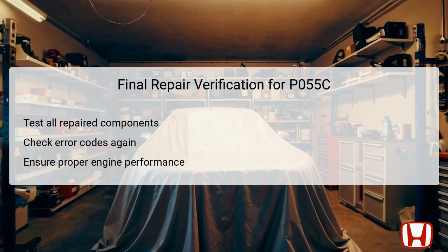After completing the necessary repairs and modifications addressing the DTC P055C, it is crucial to conduct a final repair verification. This process includes testing all components that were serviced or replaced to ensure they are functioning correctly and efficiently. The technician should recheck the vehicle's error codes using the Honda Diagnostic System, HDS, to confirm that the P055C code has been cleared and does not reappear.